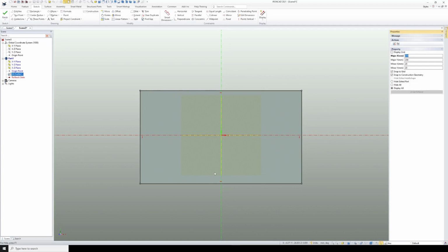So I'm going to use a mirrored constraint. So again, up in the ribbon, I'm going to select my mirrored constraint, turn it on, and then in the bottom left hand corner it tells me to select the two points that I want to be mirrored, and then the mirror line. And I'm using my left mouse button here, I'm going to select this point, and then this point, and then I want this axis here to be my mirror line, so I'll click on that. And you'll see these little indicators showing that these 2 points are now mirrored with each other.